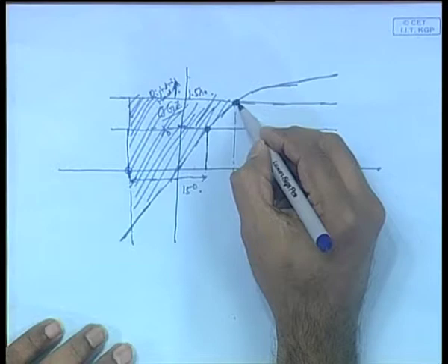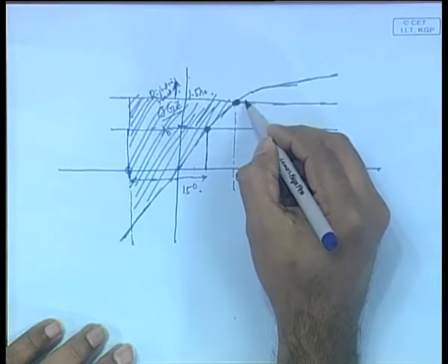So, from here, within this GZ, it keeps heeling, and what happens? Work is done again by the righting moment. Now, the wind has stopped. Okay. Wind is not acting, but the ship keeps heeling, and the righting moment keeps acting, because the righting moment is still trying to bring the ship back to its original position. When the work done by this righting moment becomes equal to that excess energy, what does it become? It stops.